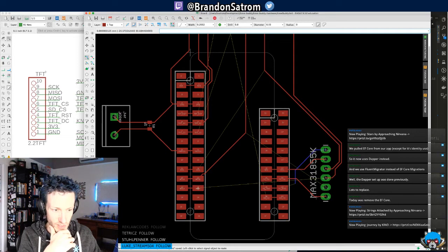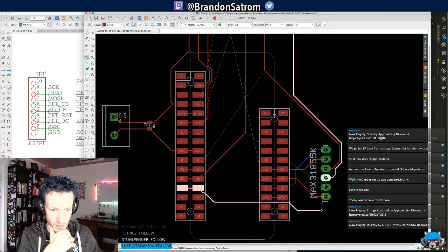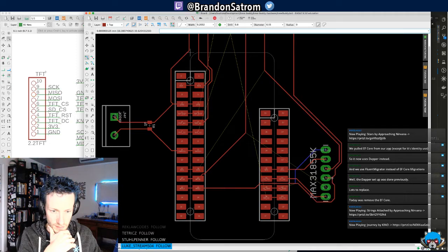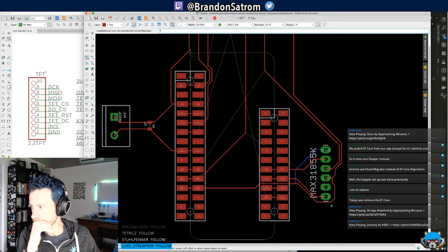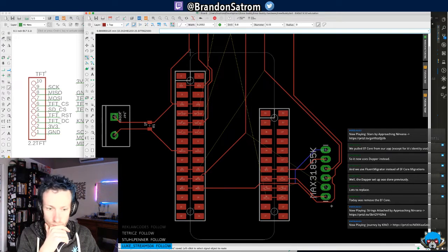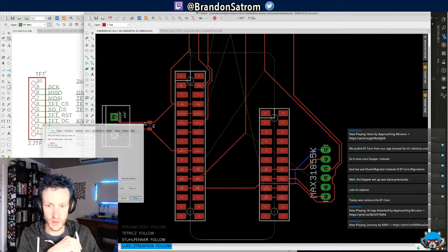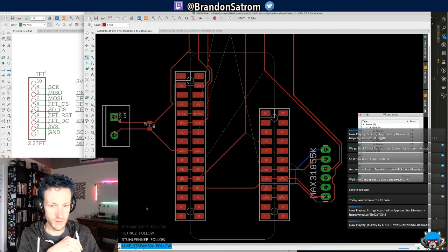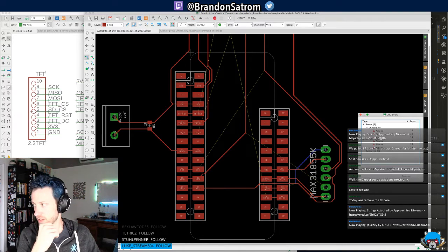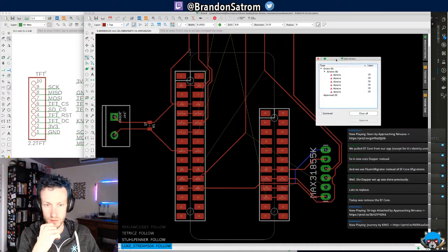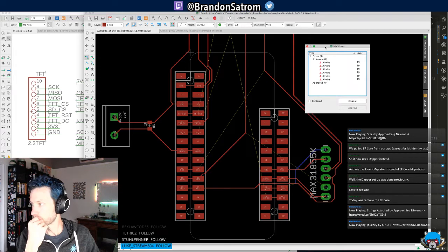So I have a MISO connection on the other side that I'll go ahead and connect. I mean, it's fine. All right. So how many do I have left here? We run the DRC again. It tells me I have 6 more to go. Throw that up there.